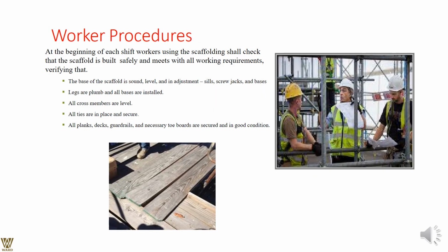Talking about the working procedures. Now, why do we talk about the work procedure? Remember, at the beginning of the shift, workers using the scaffolding self-check that the scaffolding is safe and meets all the working requirements. These are the five elements that need to be verified, and remember, it has to be done at the very beginning of the shift. The scaffolding has been built safely and meets all the criteria denoted out there.